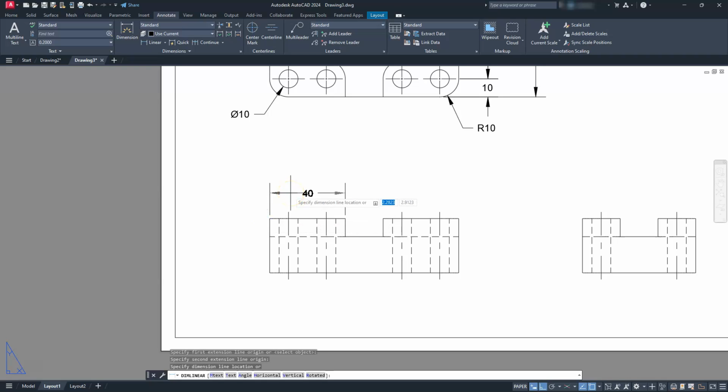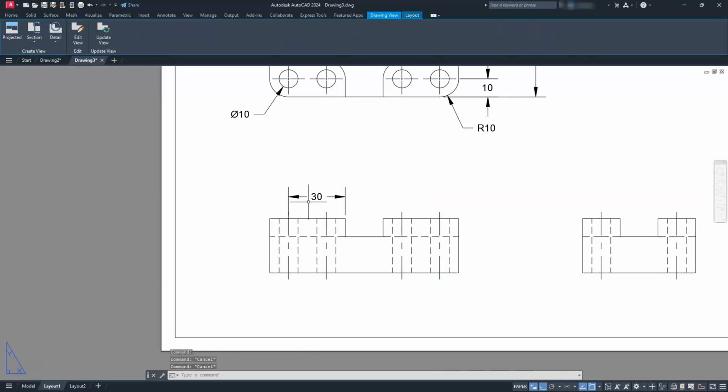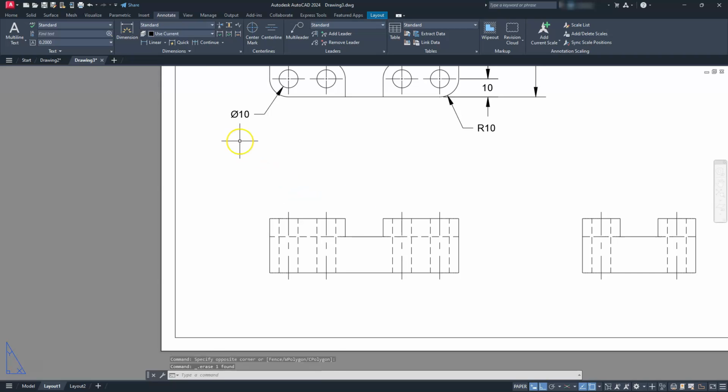Now, also, here's that other kind of neat thing about dimensioning, and I purposely deleted that. If I go to the linear, and this is one continuous line going across, just hit the enter button, and you can see that now it gives you a selection box. So once I click, it looks like that line was actually broken up. But it'll click that whole entire line there. Yep, so let me go ahead and erase that and put the linear one back. Yep, it looks like that line should be one continuous line, but apparently it's not.